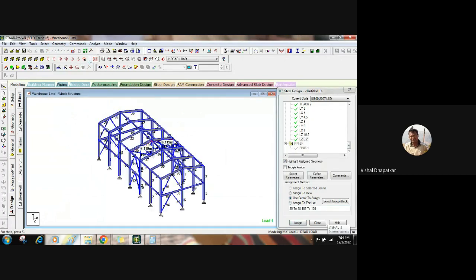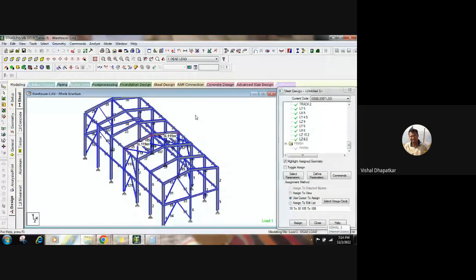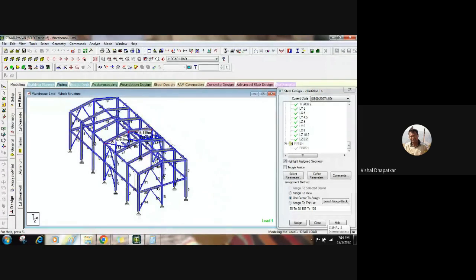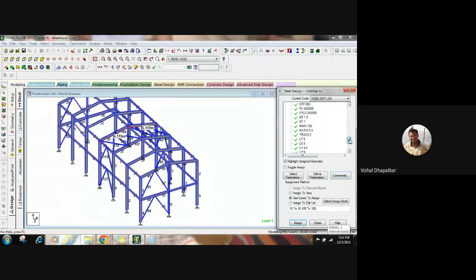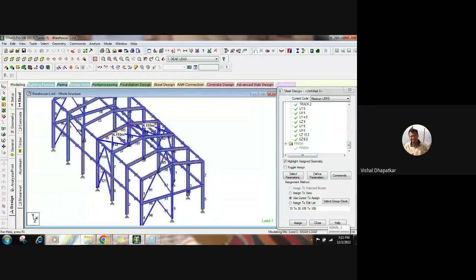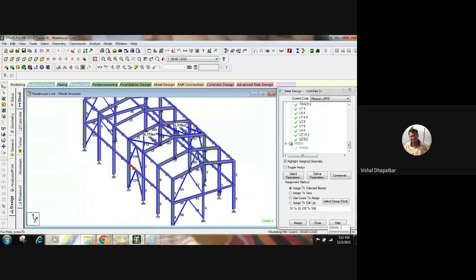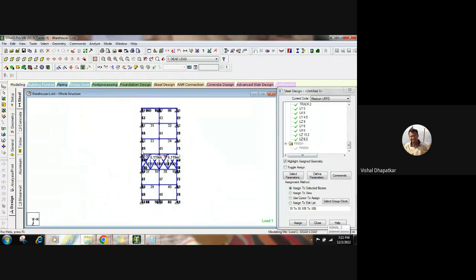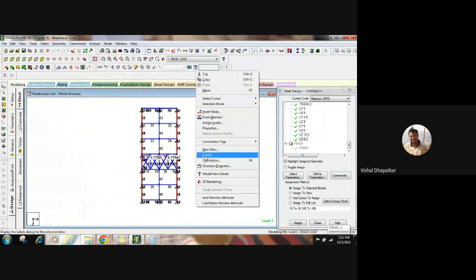Okay. So now we have assigned all the parameters. What we have to do? We have to define the check code command. So once the parameters are defined, we still need to define dj1, dj2, right? For what we need dj1, dj2? For deflection check. So only for the members where the node is created, we need to define the dj1, dj2.